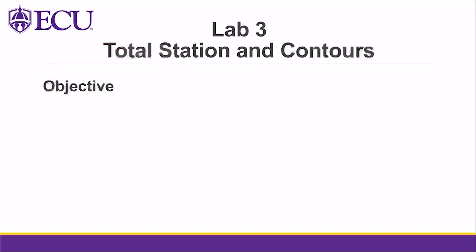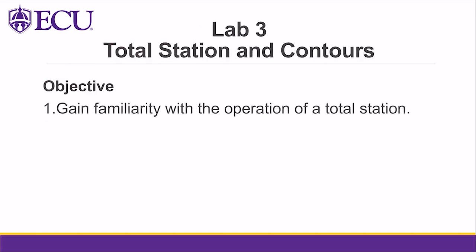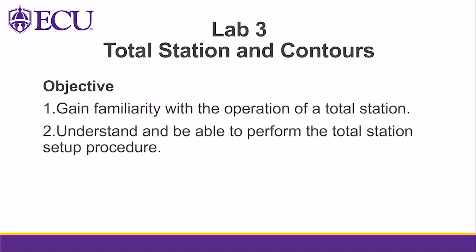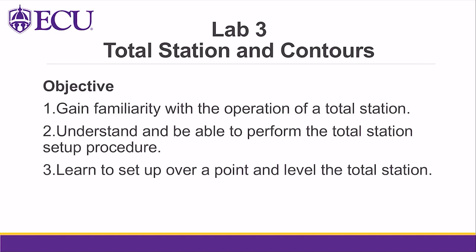Okay. So the objective is gain familiarity with the operation of a total station. Obviously, when I demonstrate to you how to do that, you will to some extent gain that familiarity. You're gonna understand and be able to perform the total station setup procedure and learn to set up over a point and level the total station.